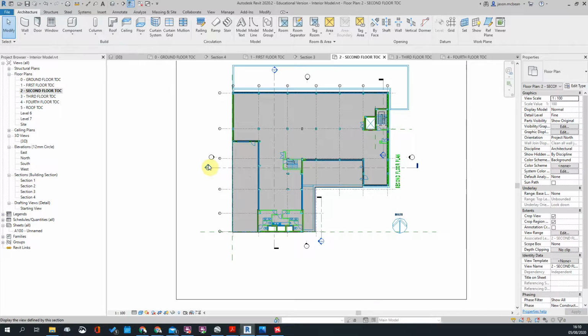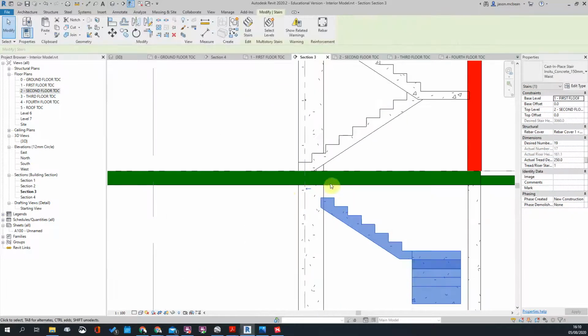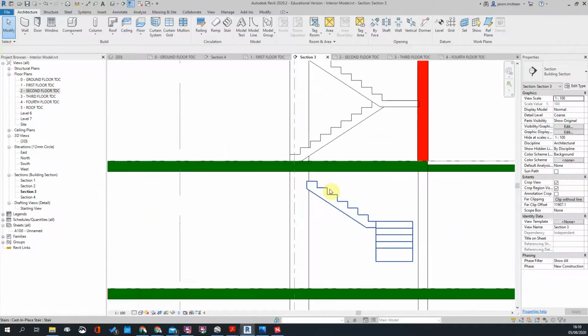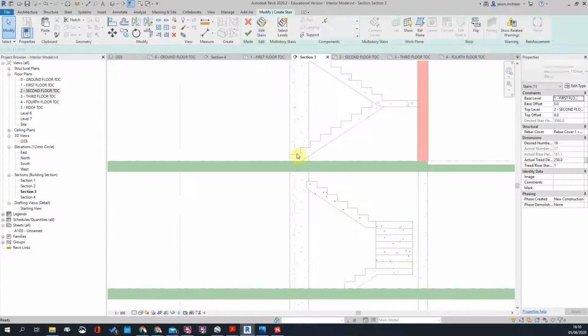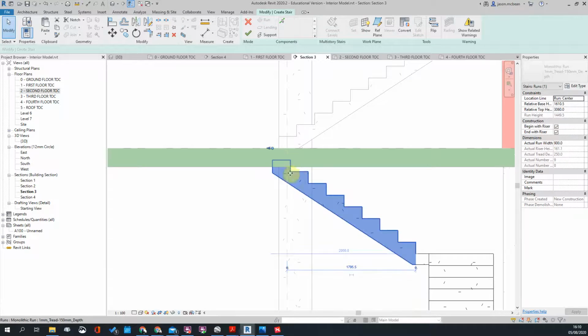let's go to my section. Now that I've got the stair working, I would assume that the stair will stop in the right place there, so I can make that adjustment here. Let's go edit. Let's see where the stair will end. Let's grab this dot, let's add. We need 2 more rises. Wow, that almost ends at the right spot.